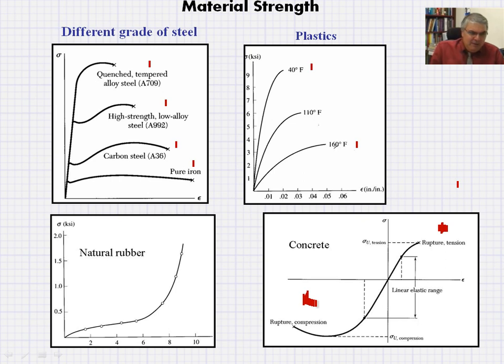As you can see, the compressive strength, and this is really not to scale, but it's provided here for illustration purposes to illustrate the point. The compressive strength of the concrete is much higher than the tensile strength of the concrete, and that's expected. In order to compensate for lack of strength in tension, reinforcement is used, making reinforced concrete a composite material.